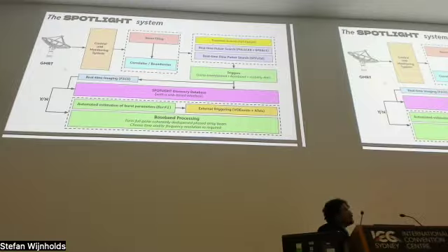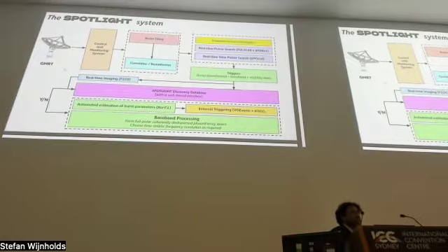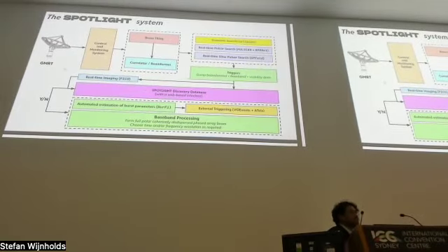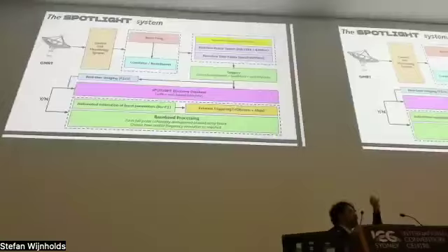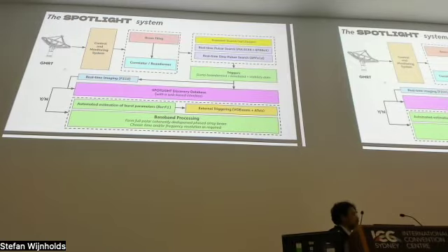First, the beam tiling will happen. The beam tiling code will form those 2000 beams in the field of view. It will check what the sky position is, what the time is, what the source is. Accordingly, it will form an optimized beam tiling map, so that the space in the field of view is used very well. There is no wastage of the field of view, I would say. And then the correlator and the beam former will do the beam forming of these 2000 post correlation beams. And then once the beam data is there, in real time we will do all the transient searches and real time pulsar searches.